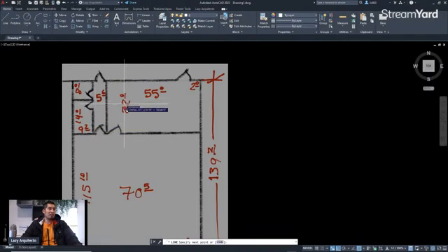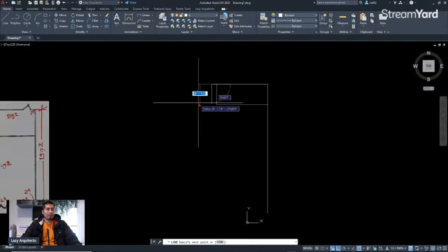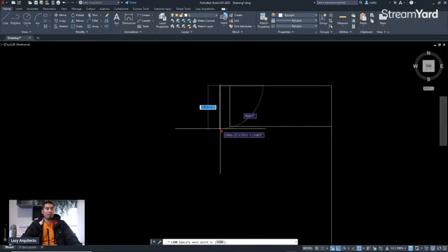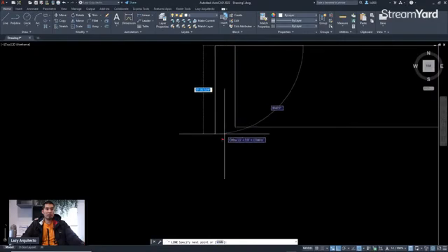You'll see that the 22 feet is also the same proportions as the corridor, so we're going to use that. I can type 22 feet, or I can simply hover over this point, over the endpoint, and then move my mouse to the side like that.